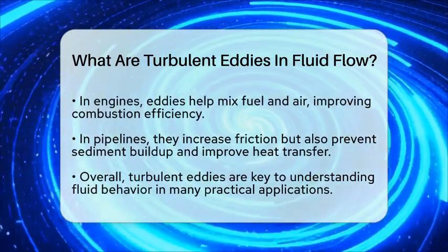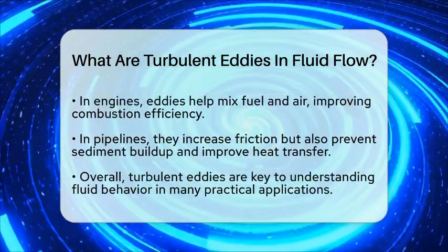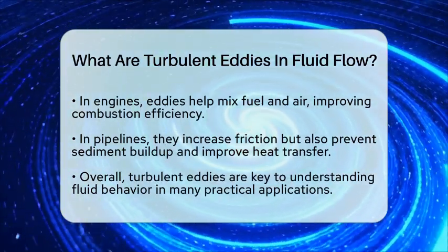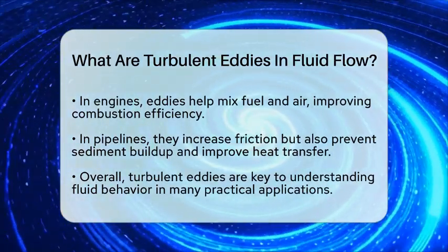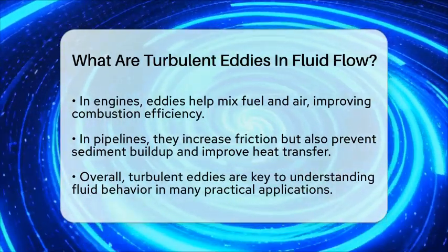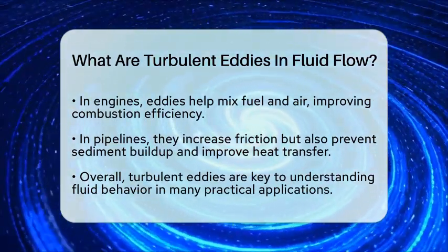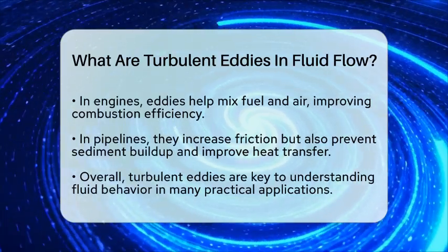To sum up, turbulent eddies are swirling, chaotic motions within turbulent flow that cause irregular velocity changes and mixing. They form when inertial forces dominate viscous forces, creating a cascade of vortices of different sizes. These eddies play a big role in many practical systems involving fluids, from engines to weather patterns, making them a fundamental part of fluid mechanics.